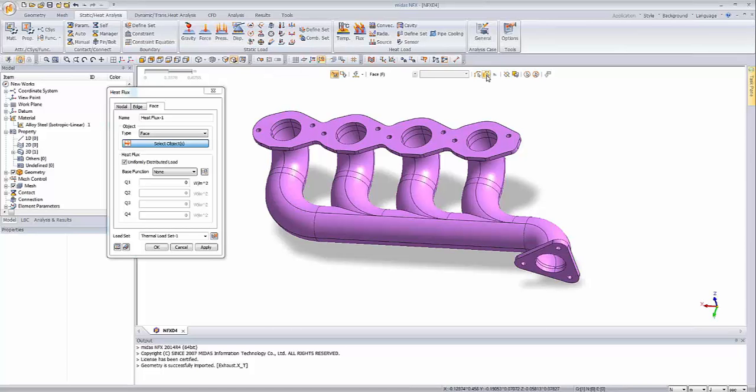So there is one option which is called select neighboring edges or surfaces with feature angle. We're supposed to start from this option and set up the feature angle. We can set it to 20 degrees, for example, or let's say 10. But I think 20 is quite a good option, and you're supposed to exercise this option by yourself.